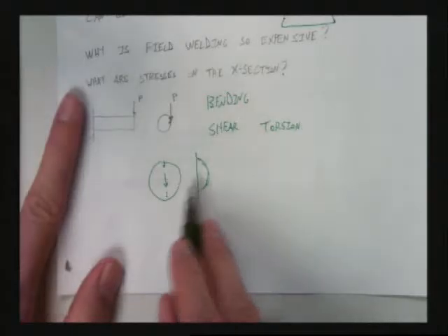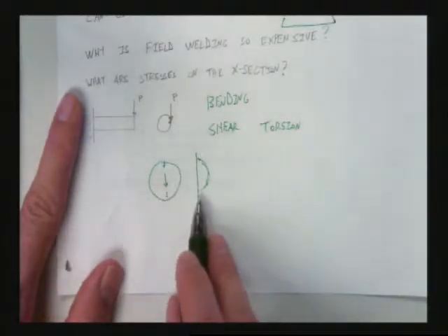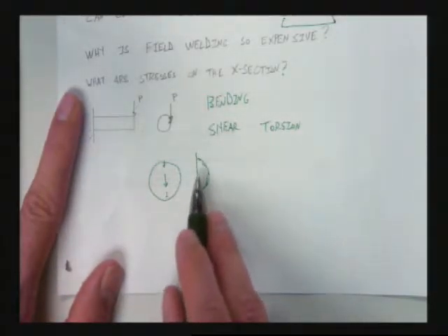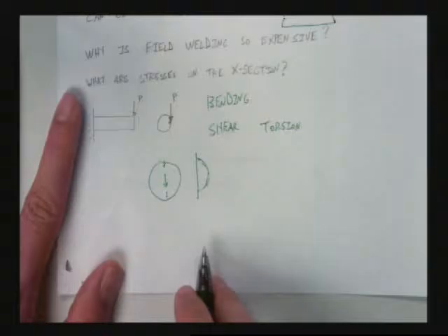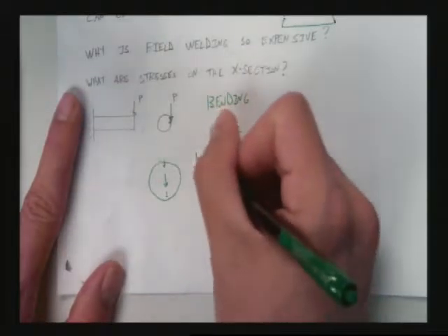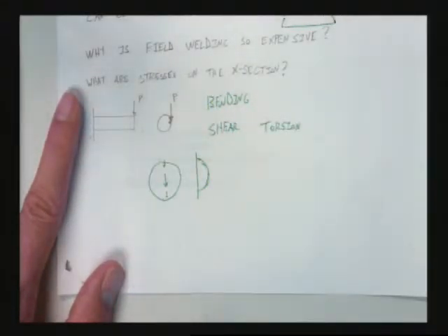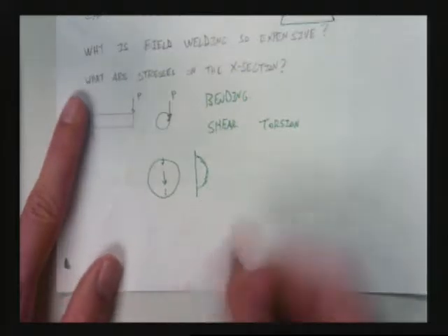They found out the problem was very, very similar to a thin soap bubble being blown on a wire rim. It's the exact same. That parabola is the exact same distribution of shear, the distribution of shear on that cross section. Okay, so that's what it looks like.